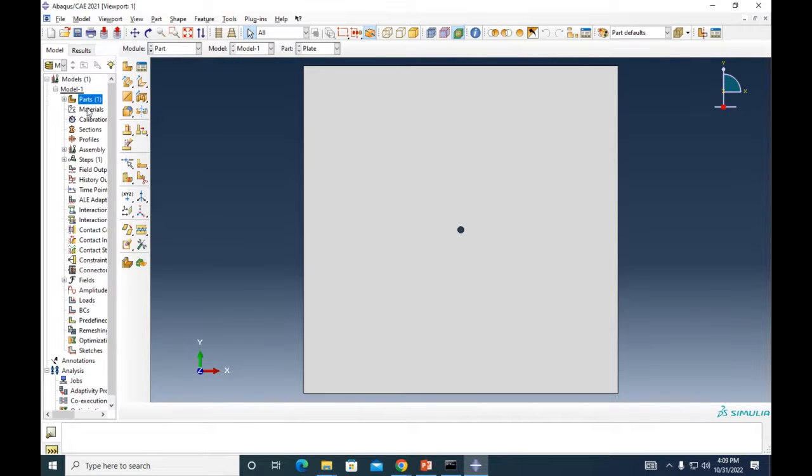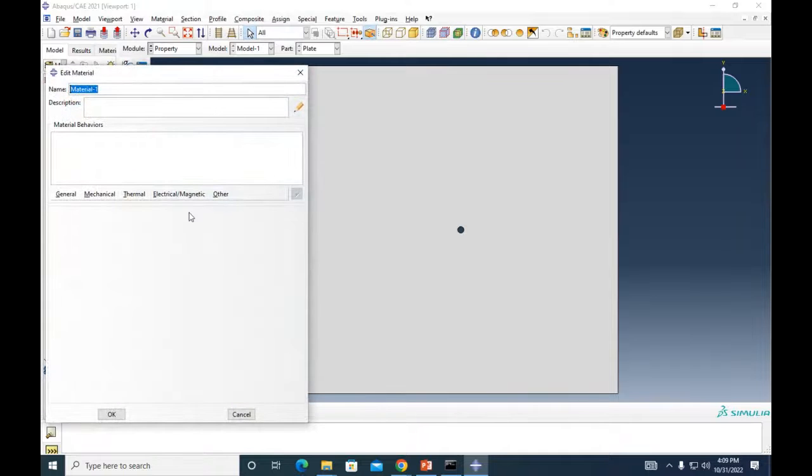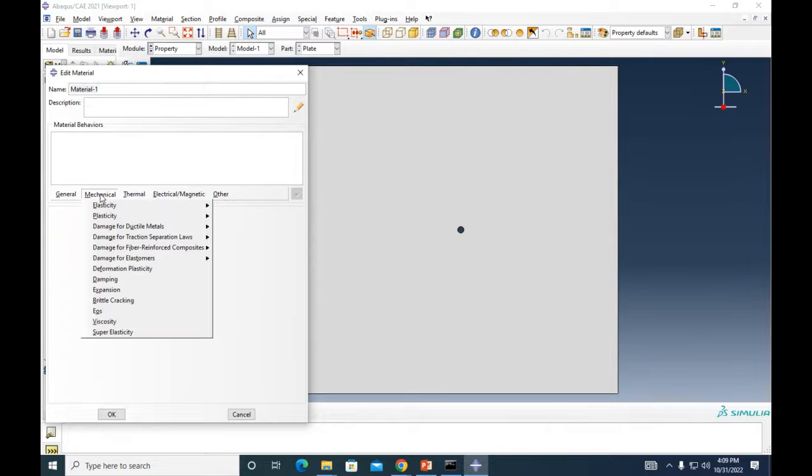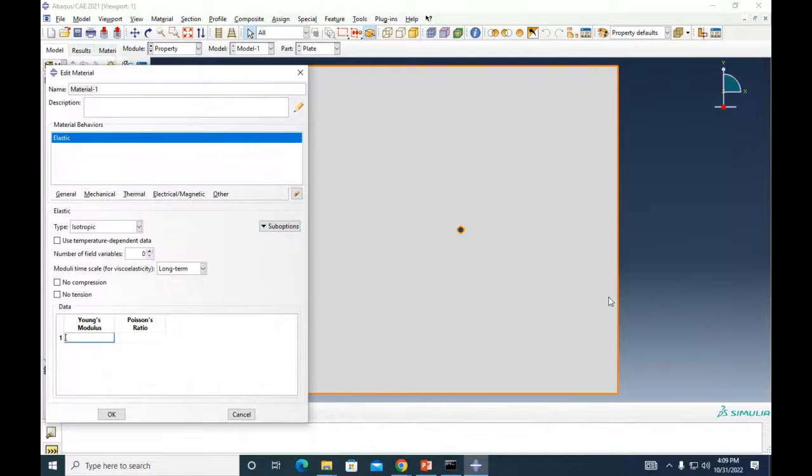Okay. Materials. Whatever material we use, the solution is going to hold, right? We didn't see any elastic modulus or Poisson's ratio in the solution, so it doesn't matter what material we use. So here, let's do Young's modulus 210 e to the 3, so steel, 210 e to the 3, and Poisson's ratio 0.3.